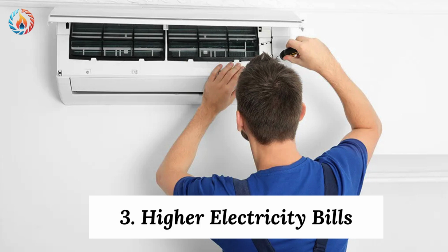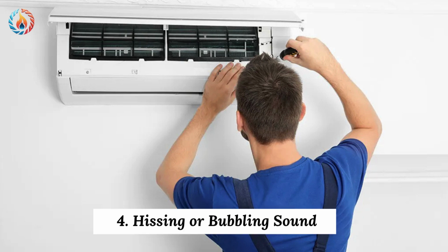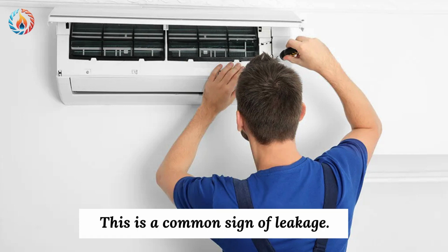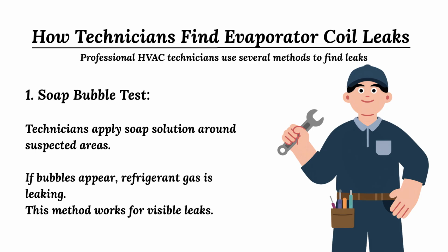3. Higher electricity bills. When refrigerant becomes low, the compressor works harder and longer. This increases electricity consumption. 4. Hissing or bubbling sound. Sometimes refrigerant escaping from the coil creates hissing or bubbling noises. This is a common sign of leakage. 5. Warm air from vents. If warm air is coming from the indoor unit instead of cold air, the evaporator coil may not be functioning properly.